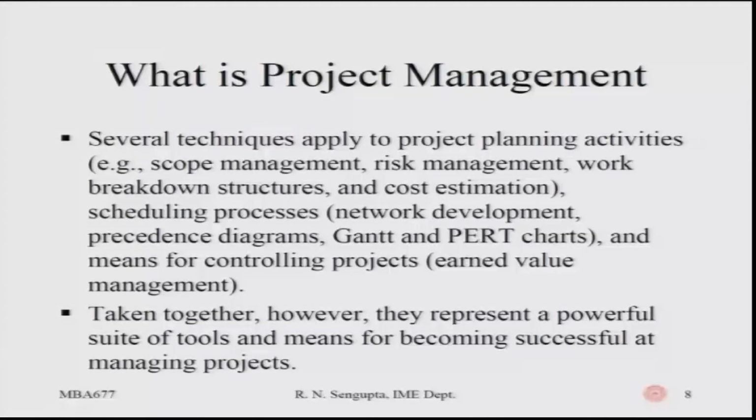We will also consider the scheduling processes, how the scheduling of the activities is done, and we will consider them in such a way that the concept of precedence diagrams, the concept of relationships between activities, which job should come before, which job should come later, how they can be taken up simultaneously or at different points of time, considering there is a time difference between two different activities or jobs, would also be considered.